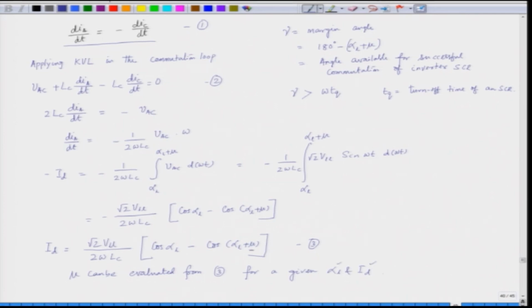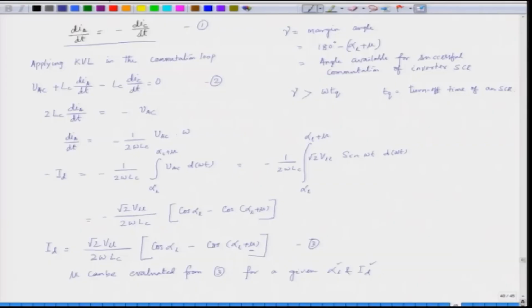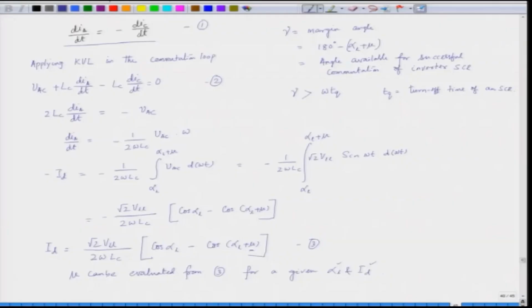Now, the commutation process causes a delay in the current, a phase lag. Now, we have a converter, AC to DC, and another converter, an inverter, DC to AC feeding the synchronous machine. Let us look at the closed loop block diagram where the synchronous machine is controlled. So, we have a block diagram of closed loop speed control.